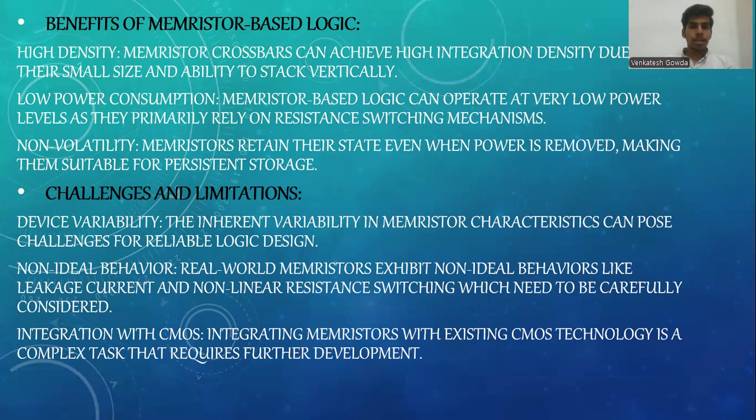The challenges and limitation on these basic logic gates are device variability. The inherent variability in memristor characteristics can pose challenges for reliable logic design. Second is the non-ideal behavior. Real-world memristors exhibit non-ideal behaviors like leakage current and non-linear resistance switching, which need to be carefully considered. At last is the integration with CMOS. Integrating memristors with existing CMOS technology is a complex task that requires further development.